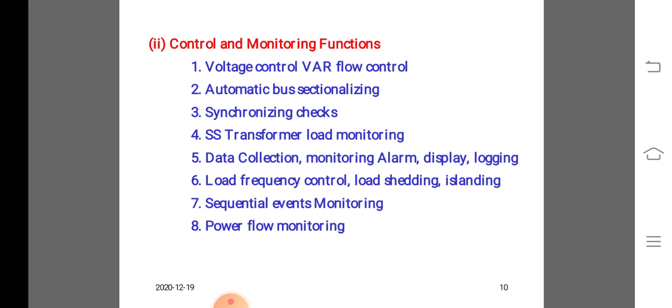Telemetry may be analog or digital. In analog telemetry, a voltage, current or frequency proportional to the quantity being measured is developed and transmitted on a communication channel to the receiving location, where the received signal is applied to a meter calibrated to indicate the quantity being measured, or it is applied directly to a control device such as a computer. Forms of analog telemetry include a variable current, pulse amplitude, pulse length and pulse rate, with the latter two being